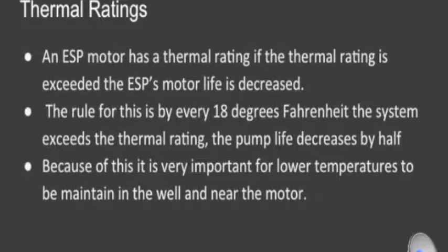ESPs have thermal ratings. If the thermal ratings are exceeded, motor life is decreased. The rule for this is that for every 18 degrees Fahrenheit the system exceeds the thermal rating, the pump life is decreased by half. Because of this, it is very important for lower temperatures to be maintained in the well and near the motor.